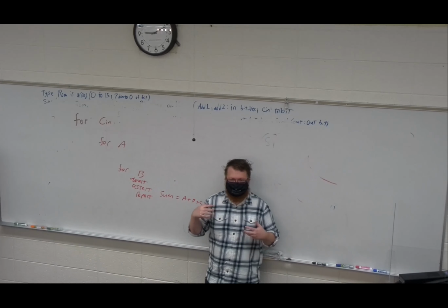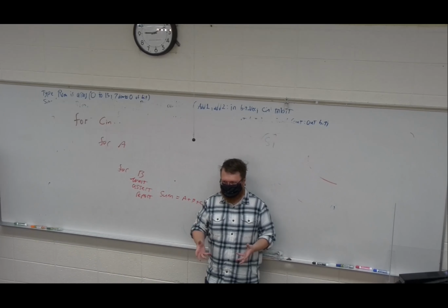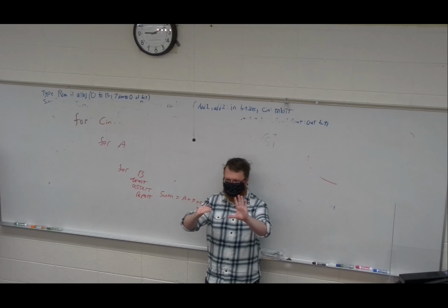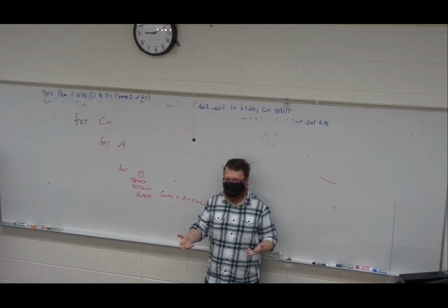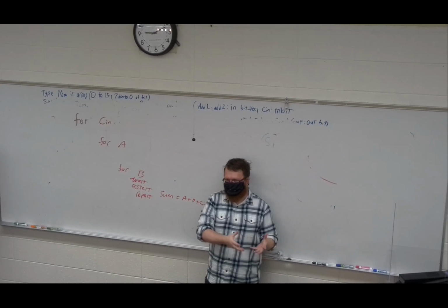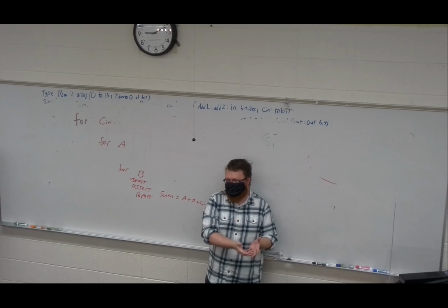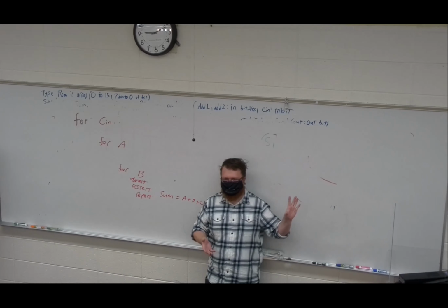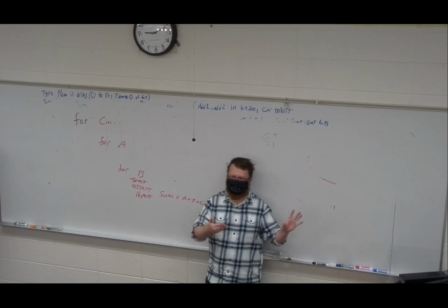When you launch a simulation, it by default shows you the top level signals. Let's say your SPI is not a top level signal and you want to know what the state is. The bad way to do it, which is what I was taught by a previous professor, is to create an additional port so that you can look at those signals.